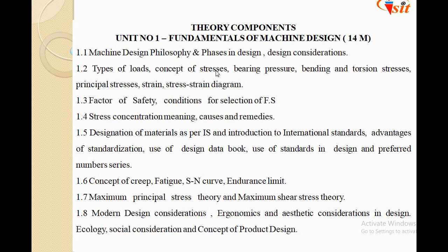We have to study this under the concept of stresses, because this is the basis for the design of any machine component. That means by taking into account the nature of stress induced in the machine component, we have to design it. So we have to study the different types of stresses: bending and torsional stresses, direct stresses, that is tensile, compression and shear, and we have to study the stress strain diagram.